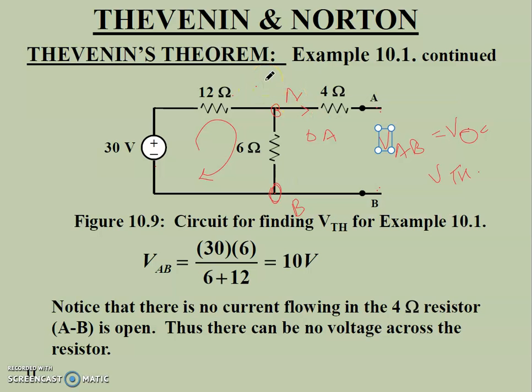Okay, so what will be the voltage across these two points? It will be 6 into I, if we consider this one as the current I, by mesh analysis. We can find it like that. I will be 30 upon 12 plus 6, means 30 by 18. That will be the current flowing through this point.